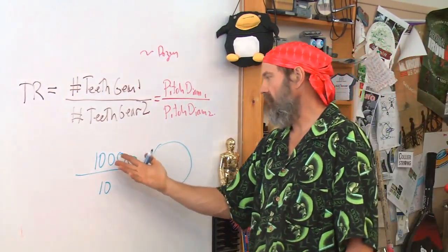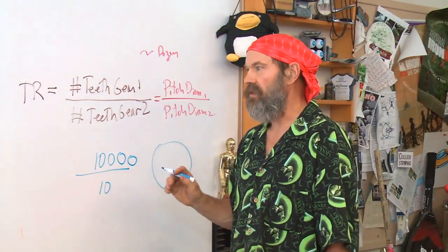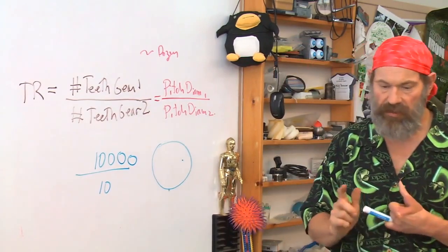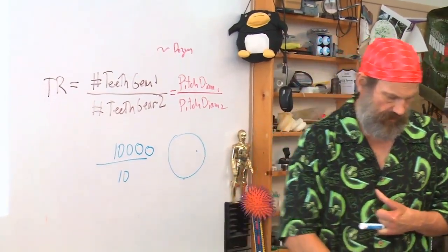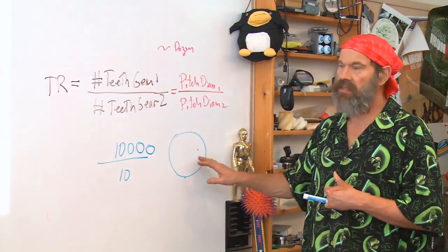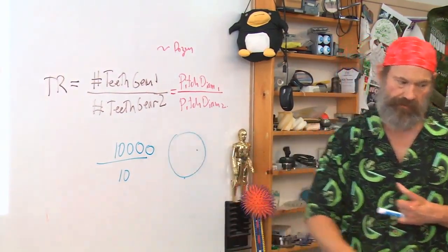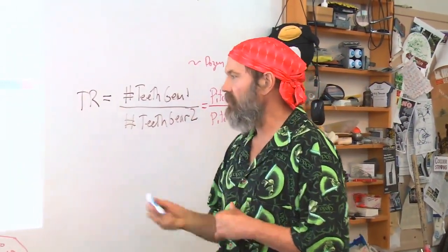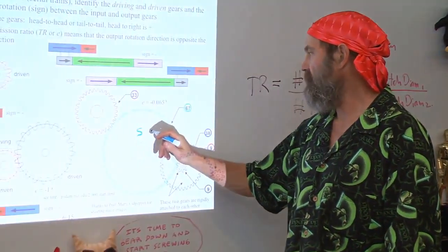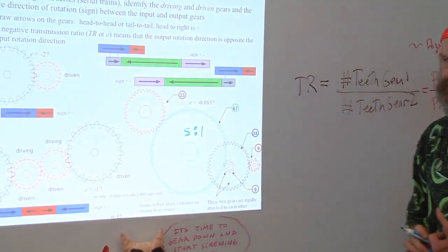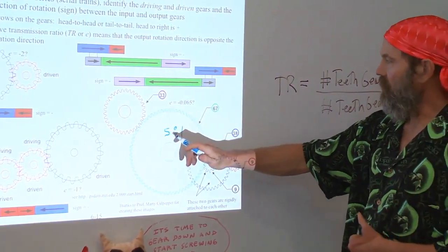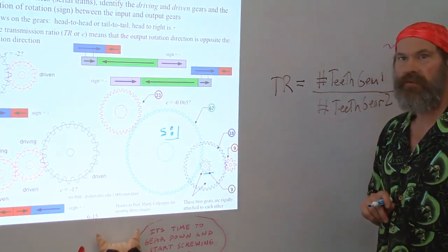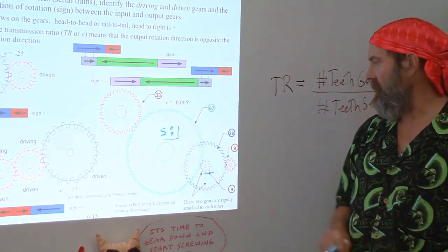How can I get very high ratios, say 1,000 to 1, by not having a monster giant gear and a little itty bitty gear? Well, the answer is you use a gear train, and with a gear train, it's very simple to do things in series. It's not unreasonable to have 5 to 1 between one large gear and the small gear, often called the pinion gear.